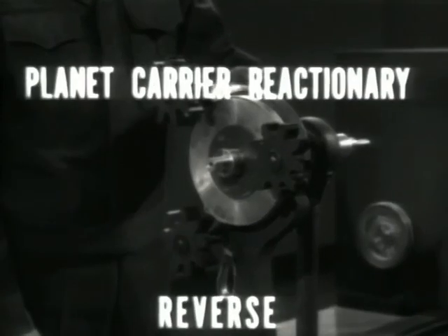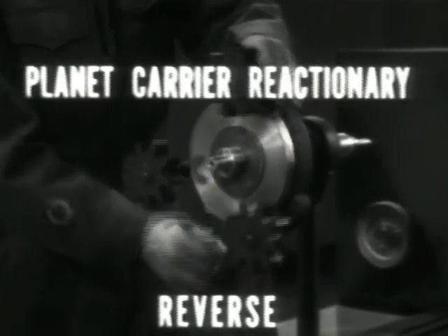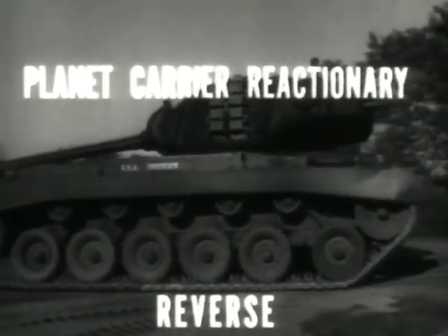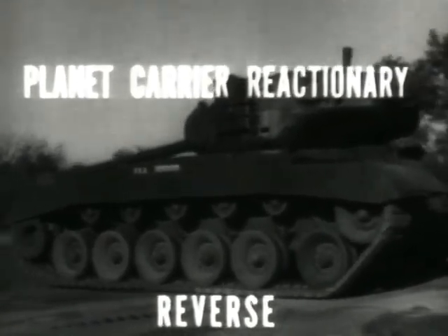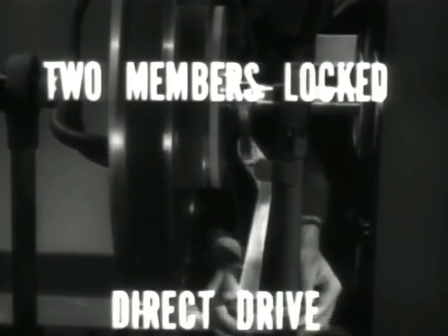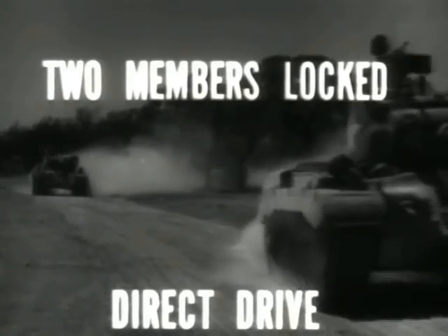Then there's law number 4. When the planet carrier is the reactionary, we get reverse. And finally, law number 5. When any 2 members are locked together, the result is direct drive.